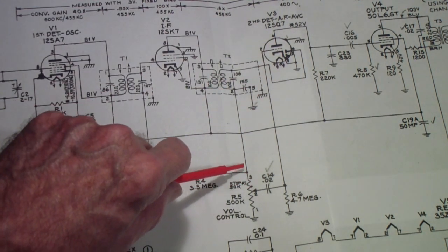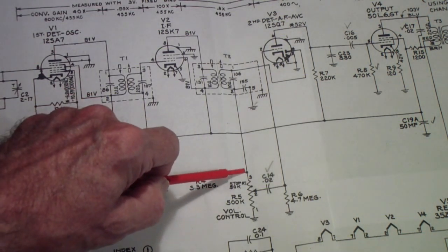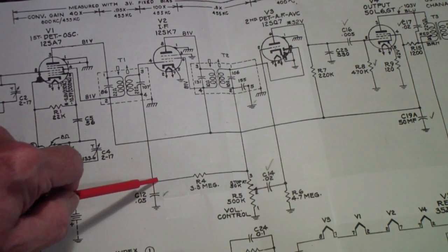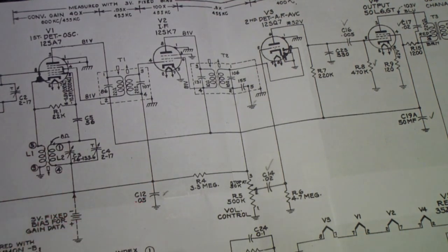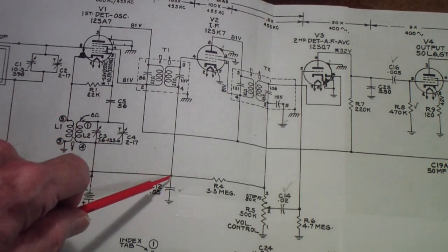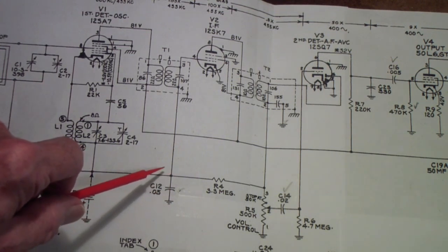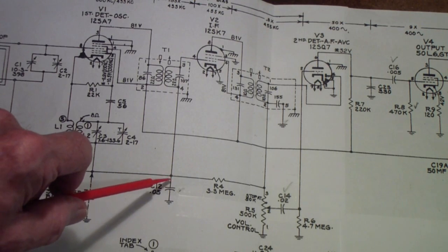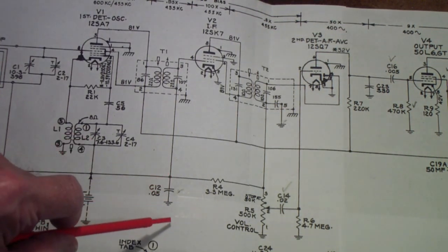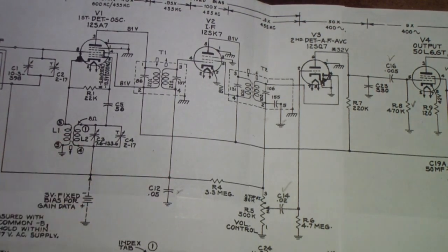But you also pick that off with a resistor capacitor filter. What that does is it averages the signal at this point and turns it into a negative voltage across this capacitor. That's what we've been measuring. The meter is connected to this point, from this point to ground. So it is measuring, and you may recall, with a strong signal, it has about -2 or a little over -2 volts here. With no signal, or in between signals, it goes down to about -0.5 volts.